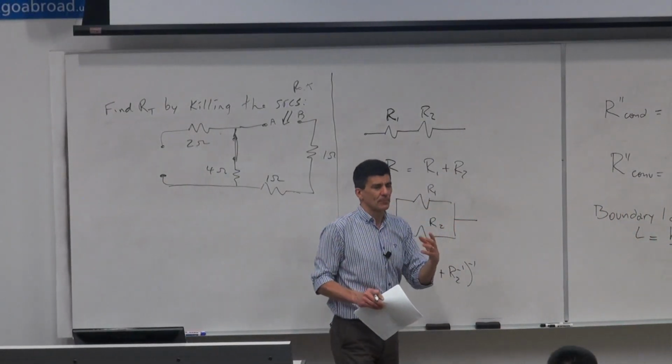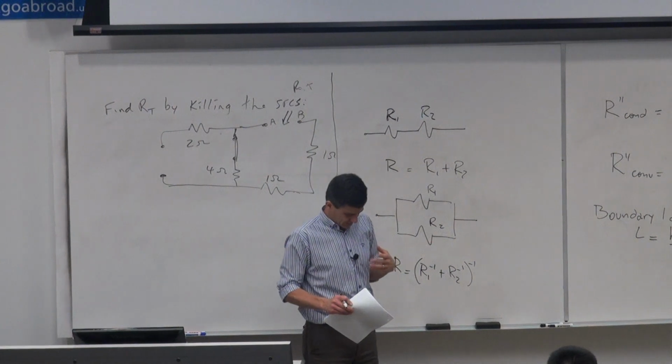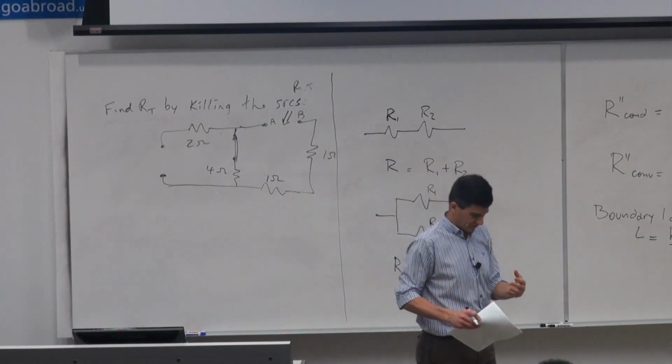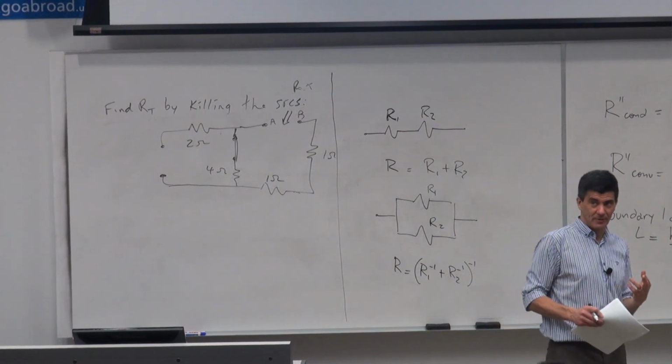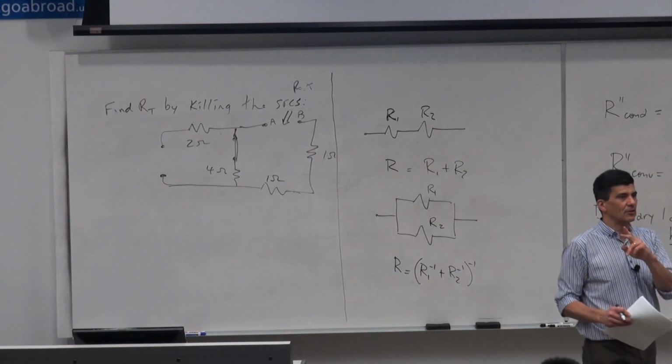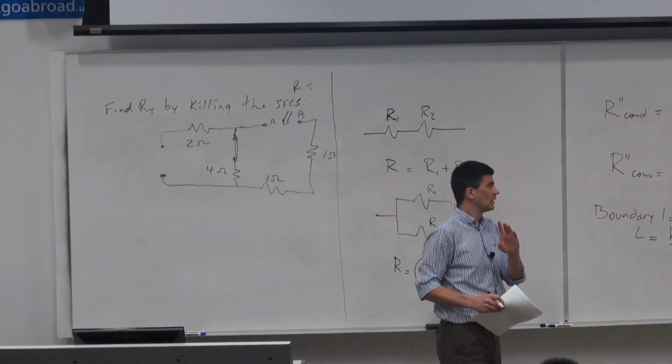For example, I have my shirt and I have convection, right? Even without a shirt, I'm not naked, right? Because I have this invisible jacket of still air, right? So now the heat from my body goes through the shirt, and the same heat goes through convection. So the conduction through the shirt and the convection to the air, those are two resistances in series, right? Okay, good.